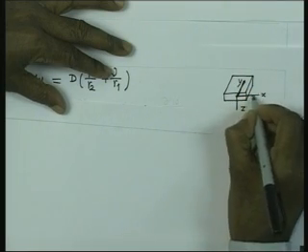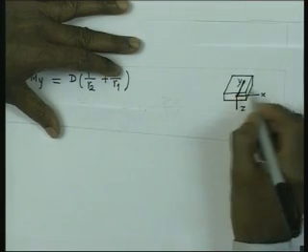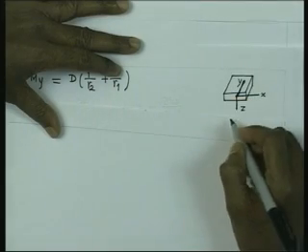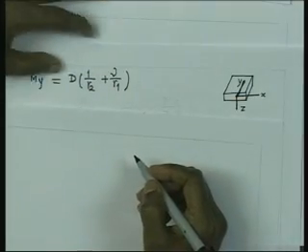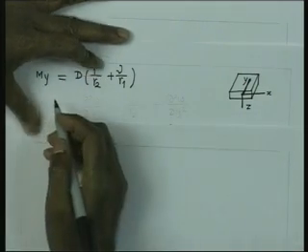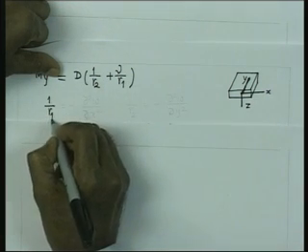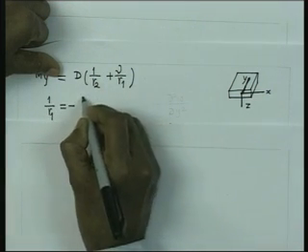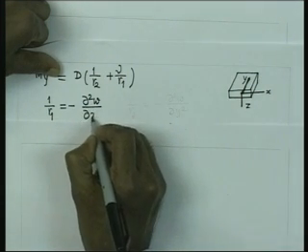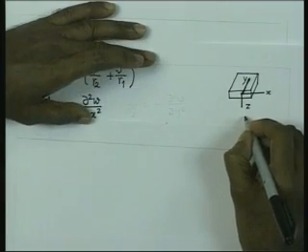So, these are the three axes, and the plate is curving in the negative z direction. That is what we have considered to be positive, it is not doing like this. Therefore, we would have the relationship between the curvature and the radius of curvature, for small deformation, 1 by R1 is equal to delta 2 W by delta x square.